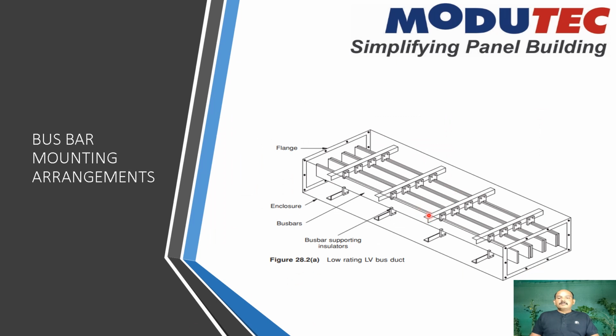If you see the bus bar arrangement, how it looks on the top view of the panel, it looks like this. This is the enclosure part. If you see, this is the bus bar running all the way here. In between, these are the bus bar supports. According to the K rating, we need to space these supports; we need to decide the distance at which to place them.